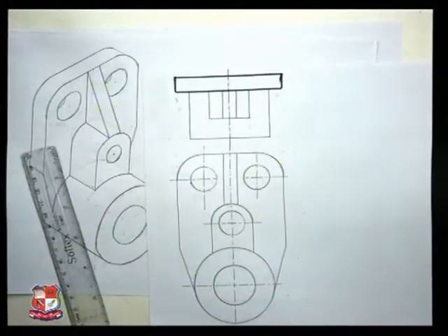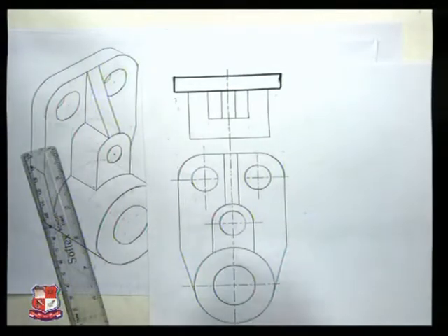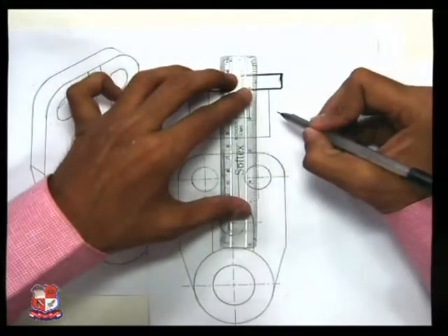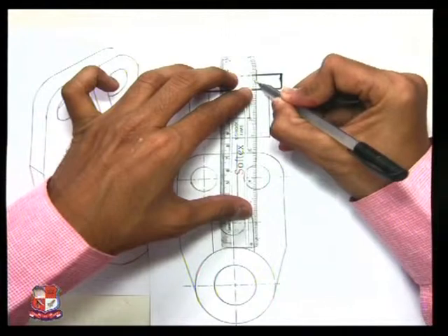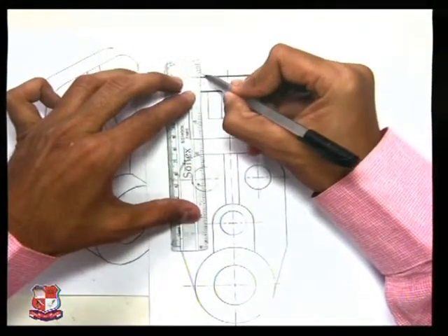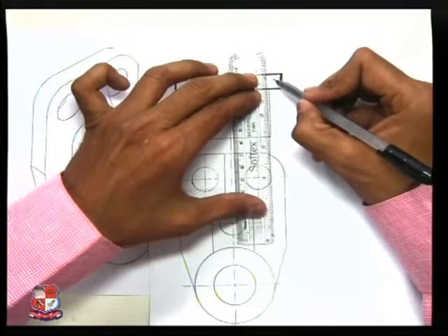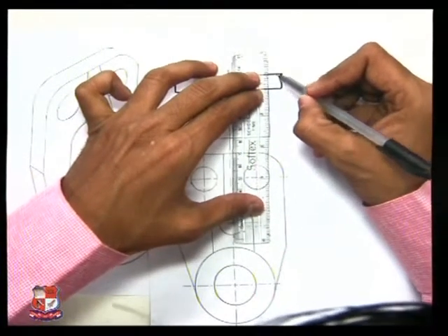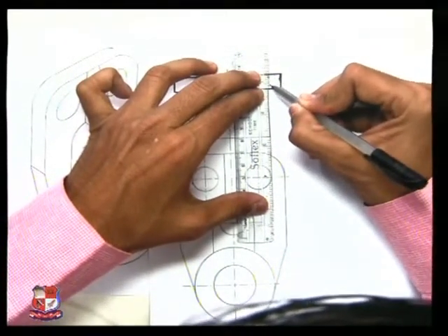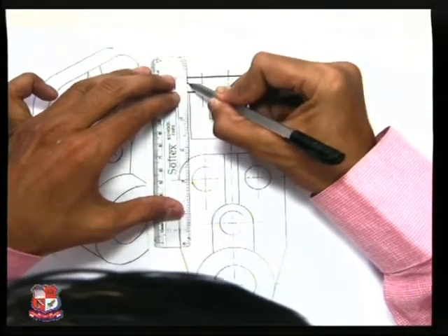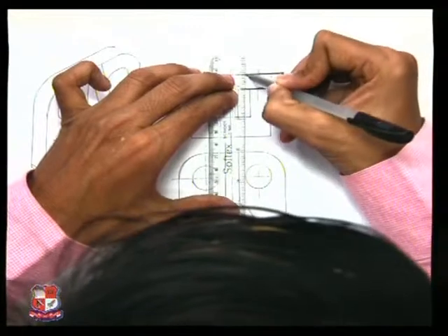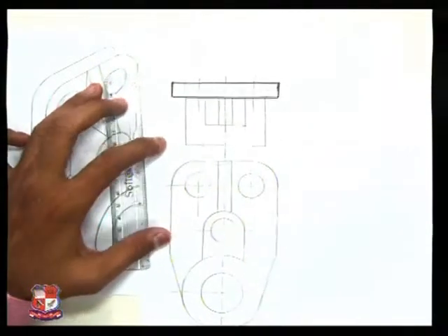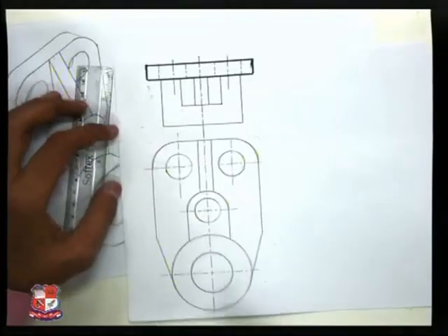Now about this portion, these circular holes, which are at a distance known to us. So for that, draw a center line like this on both the sides, and the diameter of the circular hole is given as 16 millimeter. So 8 millimeter on either side, draw dotted lines like this, and 8 millimeter on this side like this. Similarly 8 millimeter on this side and 8 millimeter on this side. So this represents the position of the circular hole which is there inside this strip.